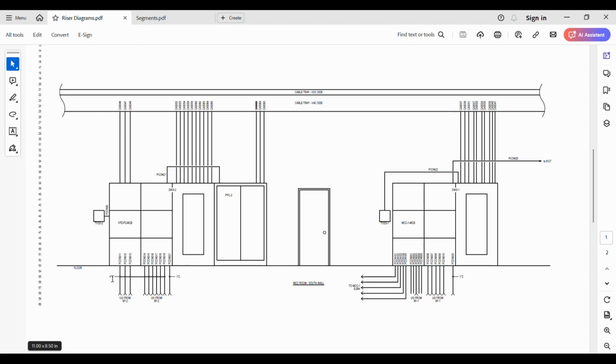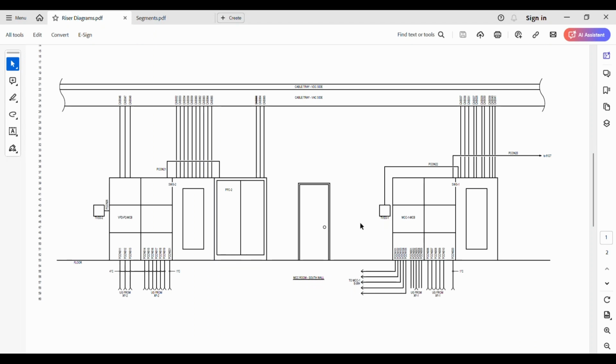This particular document shows a few conduit sizes, but in general they are just tagged with numbers, so there's a corresponding schedule that goes with it, that gives you all the details of what wires are running here, what size the conduit is, what material, what the specifications are, all of that. But you can see it completely describes the conduits to be run to and from these particular pieces of equipment in this, it looks like it's labeled MCC Room South.